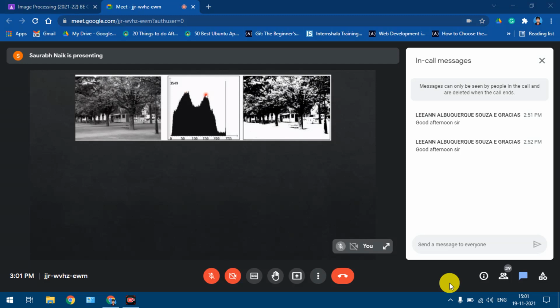Now, the mode based histogram segmentation will work only if we get a valley between these two peaks, that is some dip in this. Secondly, we can say that this peak belongs to the background pixels and this peak belongs to the object pixels, or the other way around. At least one of these peaks should belong to the object pixels. Then the other peak will belong to the background. So this valley that we have between these two peaks acts as the threshold.